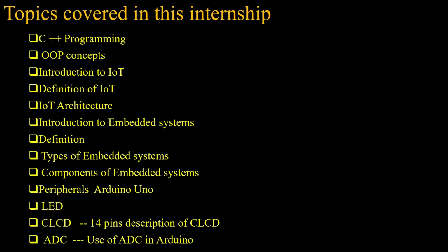Peripherals, Arduino UNO. Peripherals can be thought of as units integrated onto Arduino boards that make specialized tasks easier. UART, I2C, and SPI are some of the most common basic hardware communication peripherals that makers and electricians use in microcontroller development. The Arduino UNO board has 6 analog input pins, A0 through A5. These pins can read the signal from an analog sensor like a humidity sensor or temperature sensor and convert it into a digital value that can be read by the microprocessor.